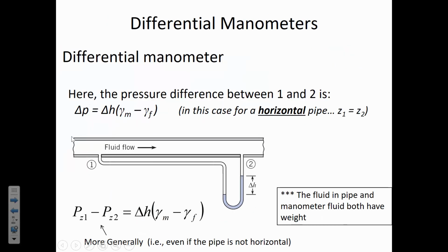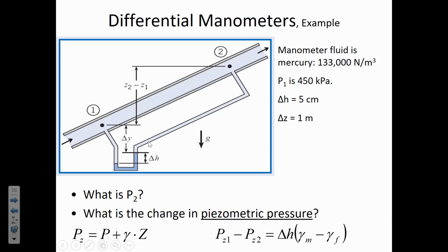You know, that's why the water is flowing from 1 to 2, is because water moves in the direction of decreasing energy. That's why water flows downhill, or that's why in a pipe, an enclosed pipe where there is no downhill, so to speak, the water flows from high pressure to low pressure. So in this next slide, the inclined pipe, part of the pressure difference is due to pipe friction, but also location 2 is higher in elevation than location 1. So there will be a hydrostatic component to why the pressure is lower at location 2. So there's two reasons there.